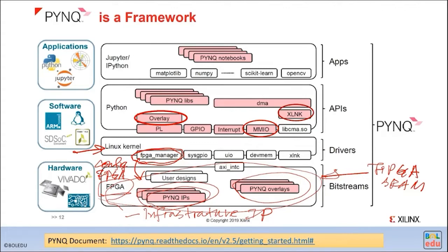The FPGA we use is SRAM based, which means all the functions in your design are configured by SRAM bits. So when we say you configure or program the FPGA function, you are loading the bitstream into the FPGA SRAM bits, and the SRAM bits are all scattered across the whole FPGA chip.